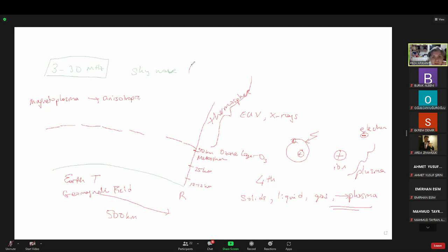In this case, your D, displacement, is related to your electric field through a matrix. Your epsilon is not a number anymore, it becomes a matrix. Because of this, the material polarization inside the system, or conductivity also, is a matrix.